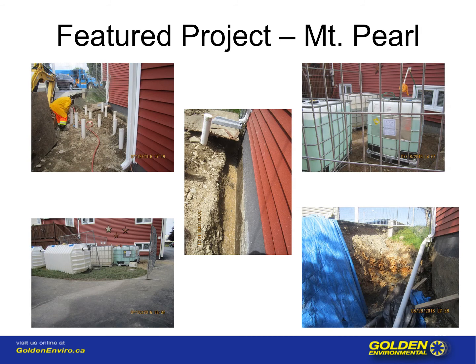Looking at the photo at the top left-hand side, we have installed injection tubes as we were backfilling. That saves a lot of time and effort, to install your tubes at the same time as backfilling. Because of the excessively high hydraulic conductivity in this lithological type, we did not need to install injection heads. It did not need to be pressurized. Everything was injected gravity feed.